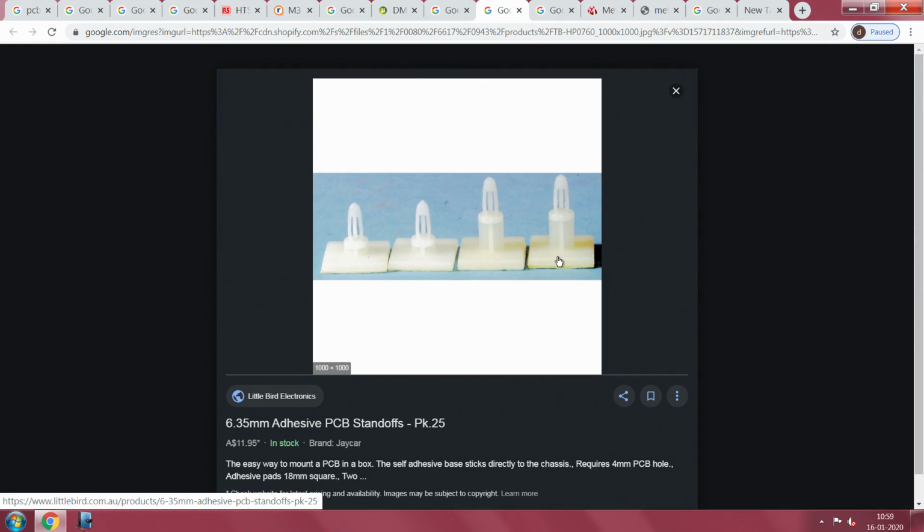standard enclosure. So, you can buy one of those innumerable standard enclosures, make another plate which is like a template, and remove this adhesive, peel this adhesive and stick them at proper places. Another way of doing it is, in case you make a jig, all these can be pushed into the jig so that the positioning will be easy, and the jig will have only openings for these items, and elsewhere you have a place for holding another thing like a tweezer. Align it and you can perfectly stick it. Later on you just need to squeeze this, remove the fixture, and afterwards push your PCB inside.